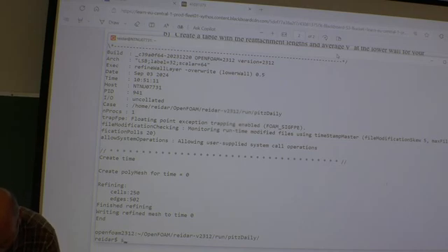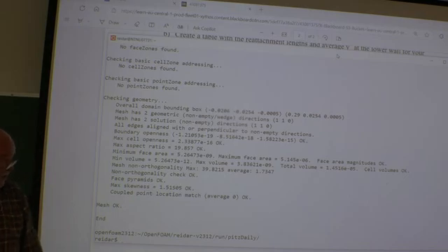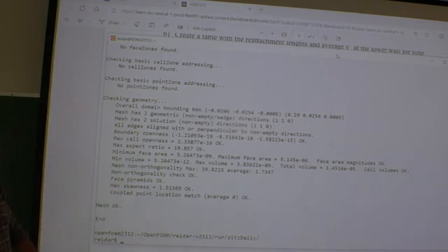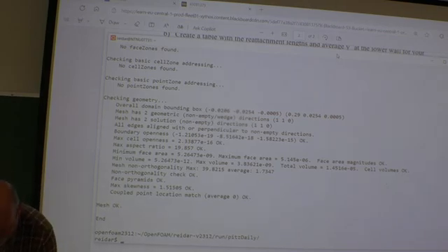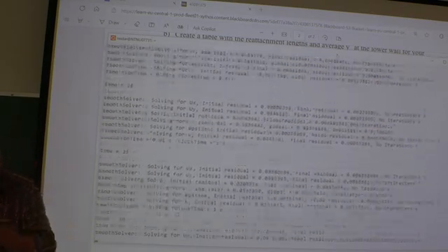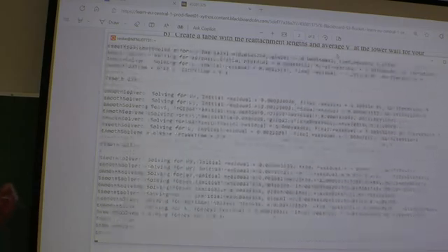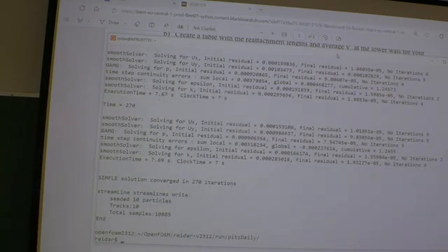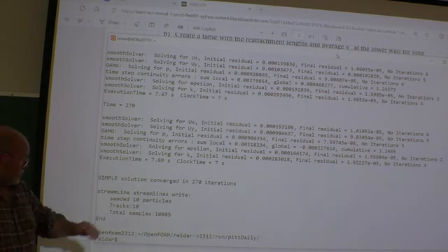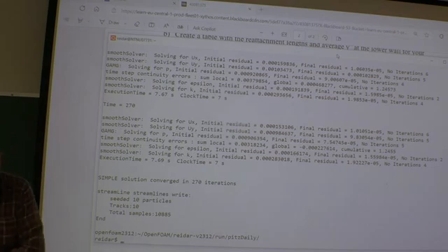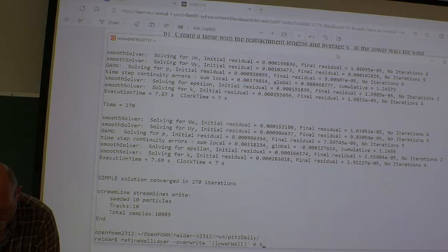Let's try to simulate anyway. simpleFoam. Let's see if we can handle it. Well, maybe we should. I think that's a good idea. Run the checkMesh. Well, the mesh is still okay. We have some more cells now, but never mind. Let's try to run it. simpleFoam. It used 270 iterations this time. Still it managed. Now let's create the y plus while we're at it.